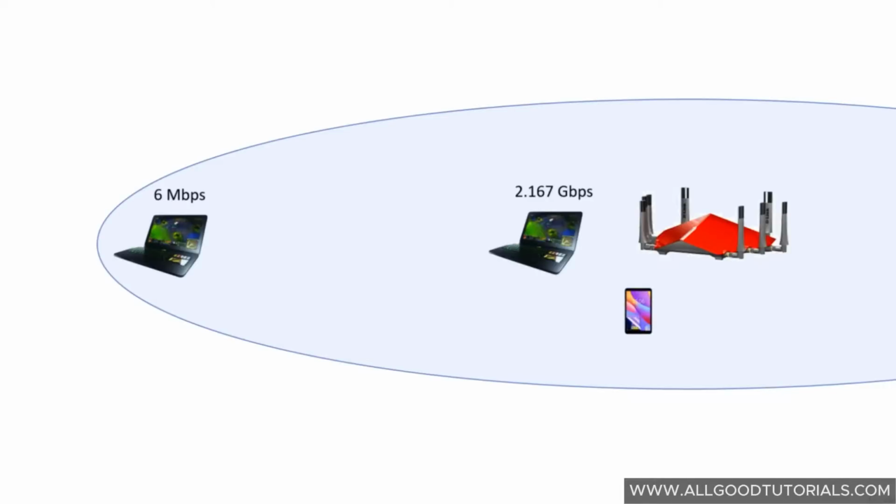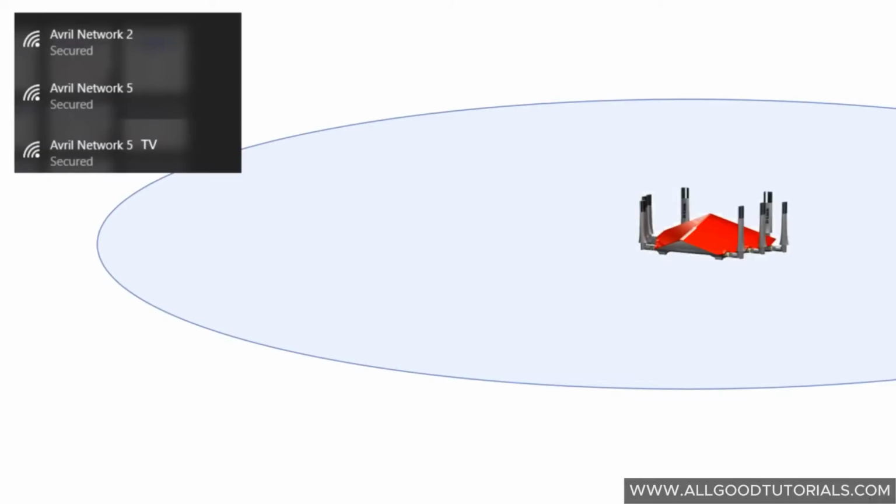For example, let's say you have a small tablet that only has one antenna and does not have 4 antennas for transmitting and receiving, then the maximum data rate that you can achieve on that tablet in good RF environments is 1/4 of that advertised data rate, and your data rates will actually be closer to 540 megabits per second. Again, that's assuming a good RF environment. If you move to the edge of the cell, again, your data rates will drop all the way down to 6 megabits per second.